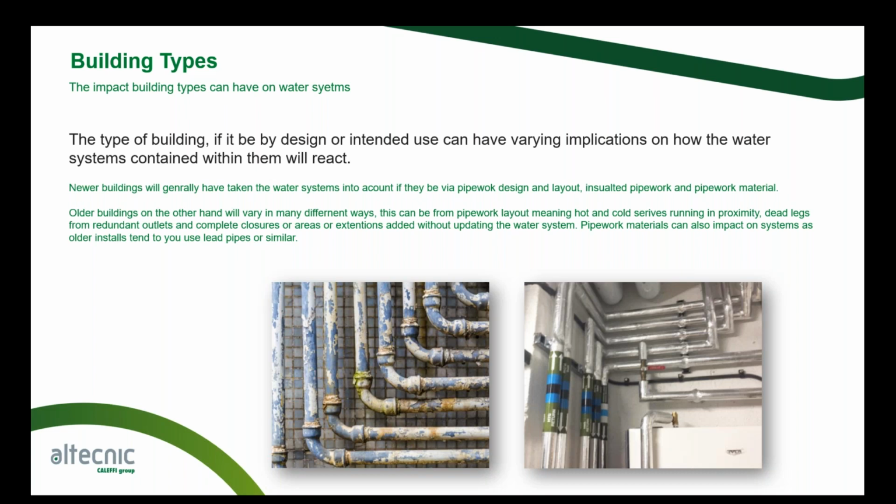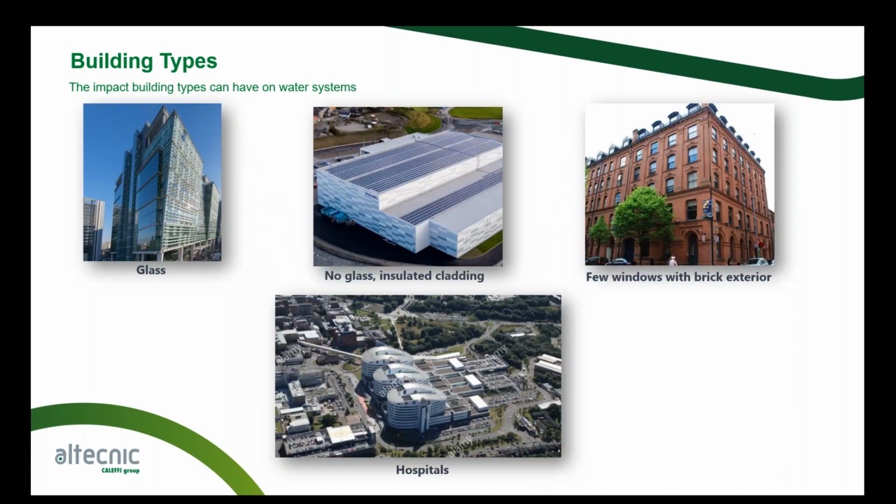We'll remove the potential problems of transitional heat loss and gains, straighter runs and whatever. So we're trying to keep that pipe as best we can, protect it from any kind of heat gains, to eradicate that bacterial growth which can come around within these sort of water systems themselves.